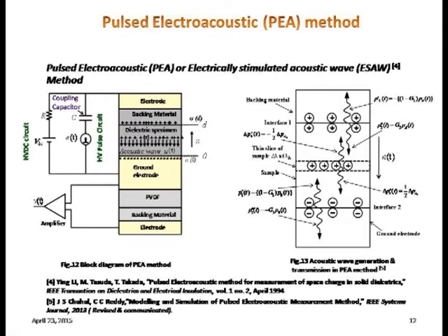See this backing material, why is it colored the same as this insulation sample? The backing material is nothing but the insulation sample only. In that, we have used some carbon particles to make it conductive, make it a conductor. So this is insulation, this is conducting, but basically the base material is the same. Only some carbon particles are used to make it conductive.